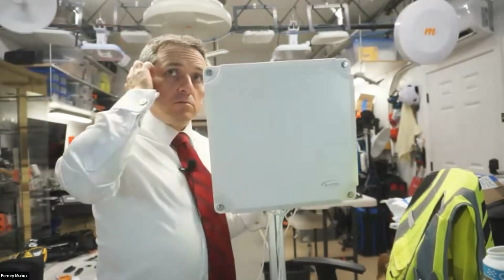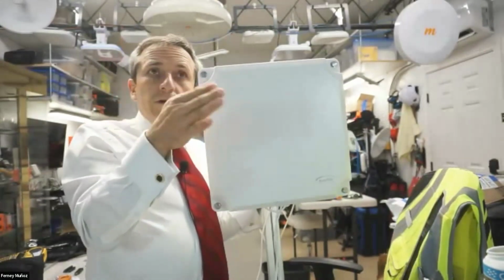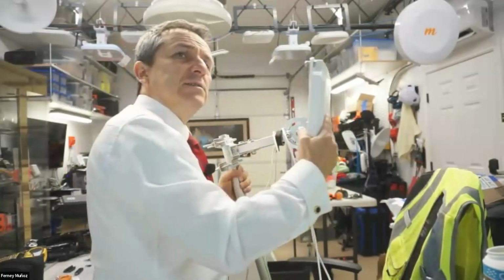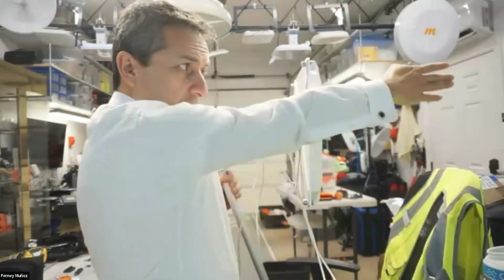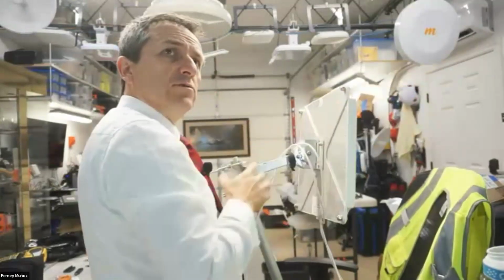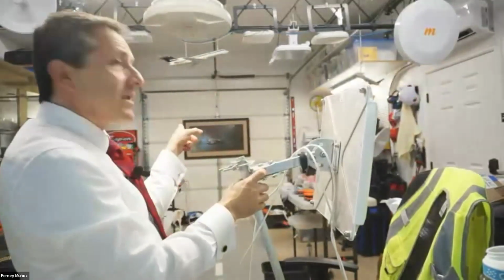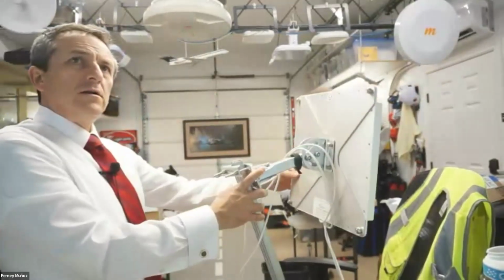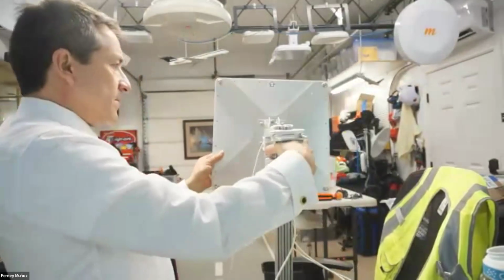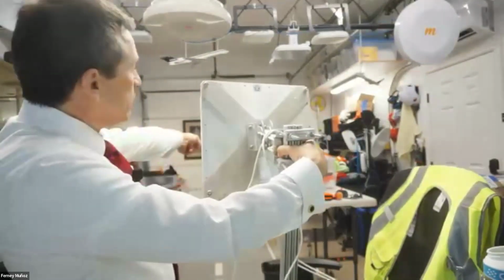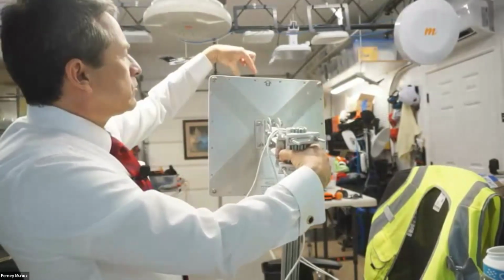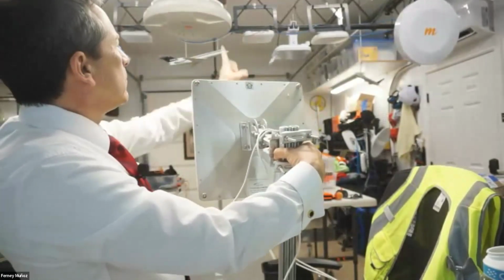The arrow that, when we move it, it changes is the azimuth. If we're gonna cover that area, then we aim it in that direction. If we intend to cover that aisle down there, my landing strip, then you turn it like this, and now it's shooting in that direction. It's a directional antenna. And the horizontal, that's the narrow part, the vertical is like this.